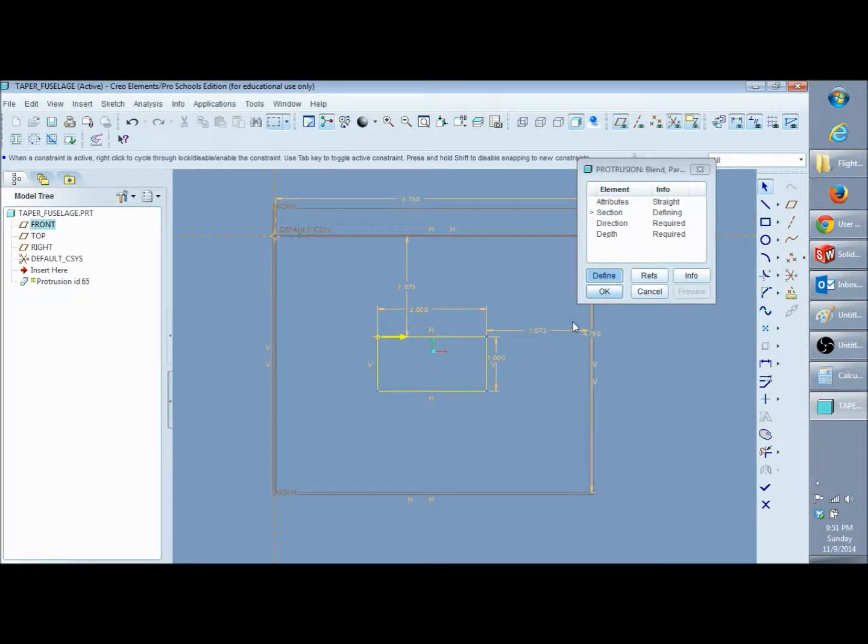There you go. Okay. So now, what I just did was that I had created the square shape. This would be the back edge. To do the tapering, let's say I want even tapering. You may not want even tapering, in which case you'll want to know how this back surface will be located with respect to the back surface of the squared off section of your fuselage.